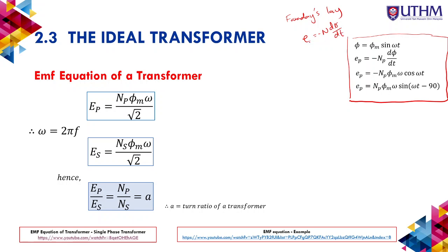So the voltage will be induced when there is a change in flux. We assume that the flux in this equation is a sine wave, and then we use Faraday's law. We try to simplify the equation, and when we differentiate, we will get this.